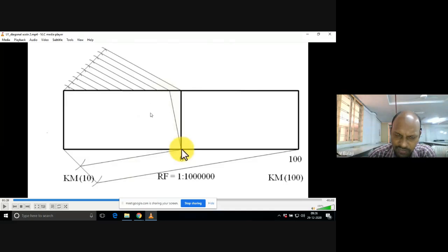But don't draw vertical lines from there, you need to use the principle of diagonal scale here. So what you will do is, after the 0 line, you would get one inclined line, right? One parallel line. From that point, you need to join to the main zero line, the main part, down below this first box. Okay, you have to join. This is the first line we are supposed to draw. And parallel to this, you set your mini drafter scale.